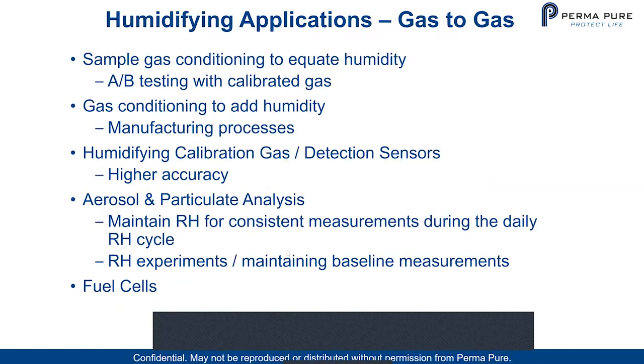So let's look at some humidifying applications for gas to gas. Number one, sample gas conditioning, to equate humidity, A/B testing with calibrated gas. There are some analyzers that have this built in. Gas conditioning to add humidity: there are a number of manufacturing processes that we support with humidifiers that add humidity to gas streams. We humidify calibration gas, particularly for gas detection sensors, for higher accuracy and fewer false alarms on gas detection.